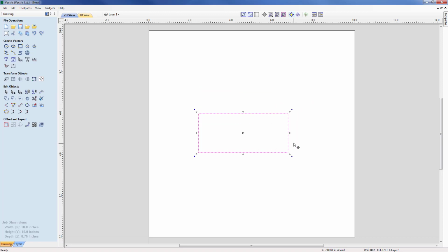Okay, so with that, I can of course specify now this distance here. As you can see, I'm moving it in X, and I can specify the length of the rectangle. So in this case, I might say that I want it to be 5 and hit return. And as you can see, that's scaled that, so that X distance is now 5. Or maybe in the Y, I maybe want to bring this down to be 1. So I simply hit 1, return, and that will have just a height of 1.